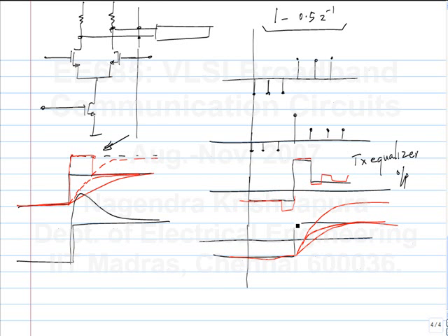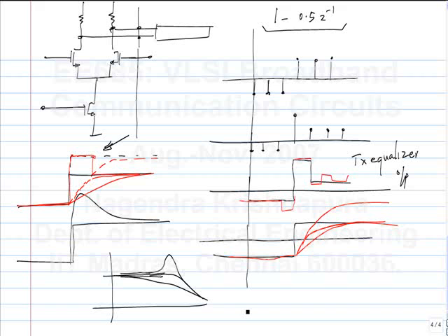Have you seen step responses which look like that? A second order system which has some peaking in the frequency response, basically an underdamped second order system, may do that. That's one possibility. Sometimes you can use that, because if you make a second order low pass response, you can have something that is maximally flat, which shows some ringing in the time domain. You can have a large amount of peaking, which will have a lot of ringing in the time domain. Or you can have overdamped stuff, which will be more sluggish, which you don't want for this. So you can try to introduce peaking in the frequency response.